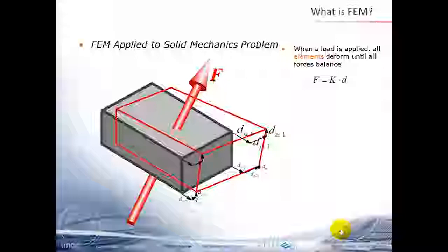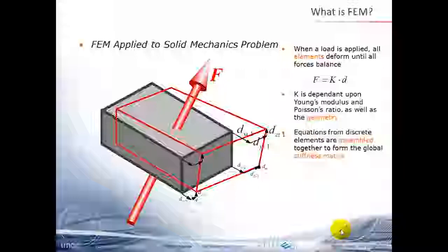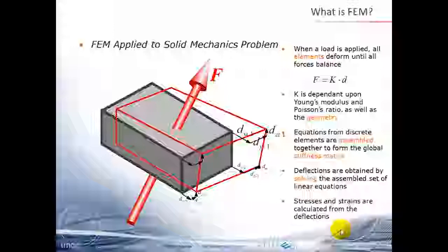Normally for a linear spring this is linear, and now we can actually write it for every node, and we write it for every element. So this gives the full matrix, and this matrix can be solved by mathematical solvers. And from the solution you can calculate depending variables like the stresses and the strains.